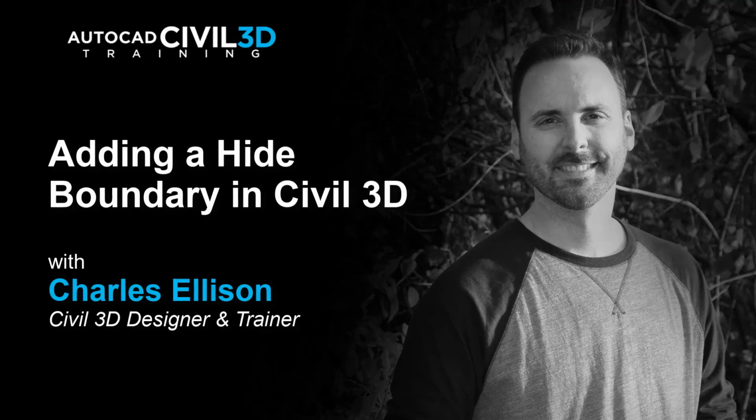Hide boundaries mask areas of the surface so triangulation and therefore contours are not visible in the area. Use hide boundaries to create holes in a surface, for example, to mark a building footprint. When you use a hide boundary, the surface is not deleted. The full surface remains intact. If there is a surface TIN line that you want permanently removed from the surface, use the delete line command.